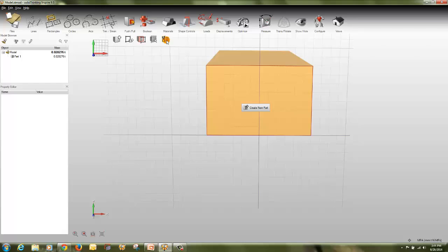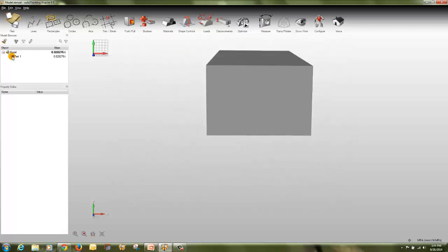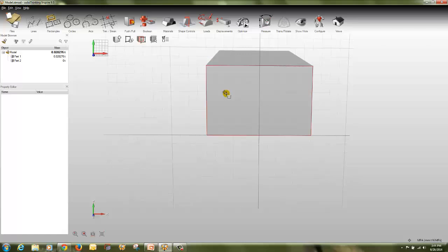So this is the sketch plane. The first thing is the sketch plane, so I'll show you. I'll click on create new, so it will create a new part. We will create a circle with the center, right click it. Again, without exiting, we will create one more circle, right click and right click.